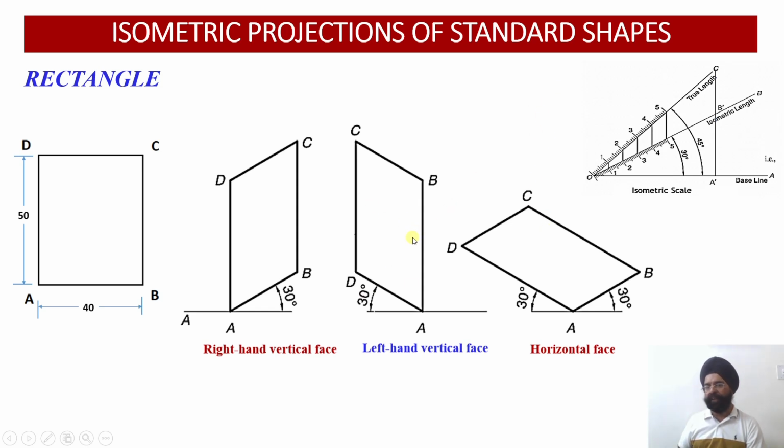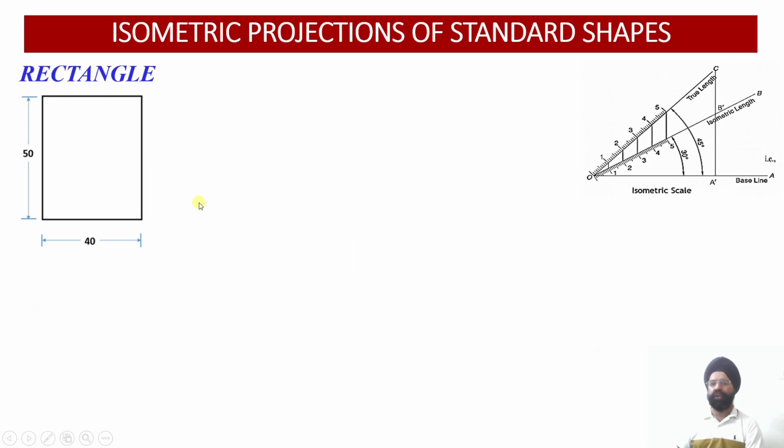Then in the left hand face, we are going to use the x-axis and the y-axis to get the construction, so that we can look at this surface from this side, and the depth will be drawn on this side over here. Similarly, for the right facing, we are going to use the z-axis and the y-axis to complete the construction of this figure of the rectangle, and then we can look from this side, and the depth of the solid, that is the prism, we are going to draw onto this particular orientation, right? So let us start drawing all these rectangles in different orientations.